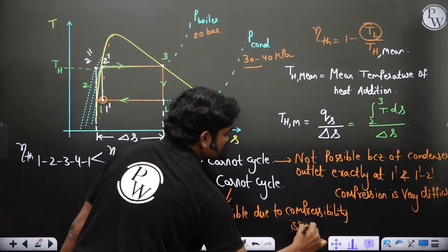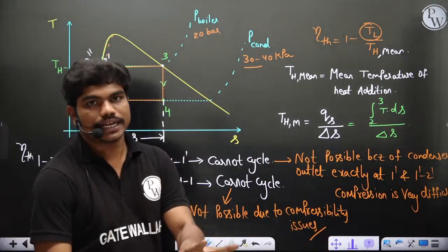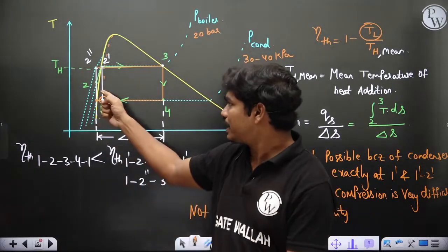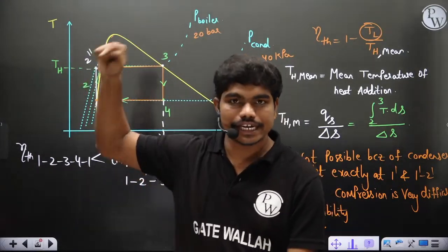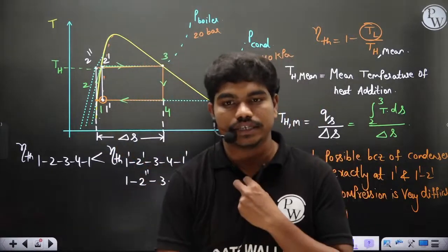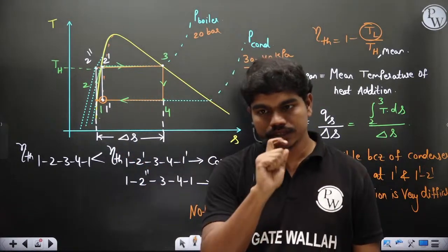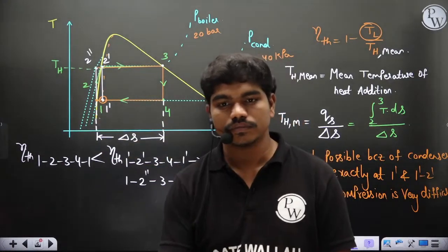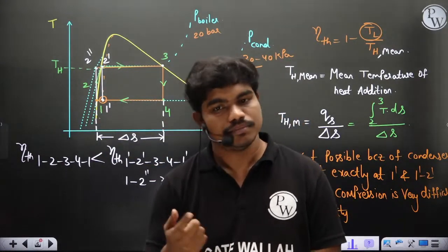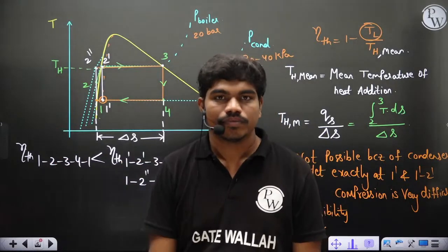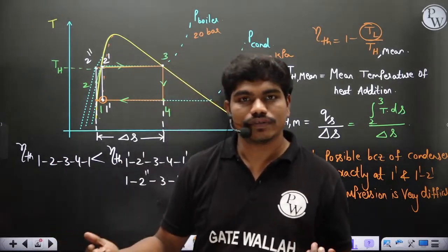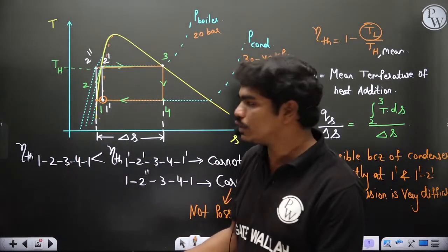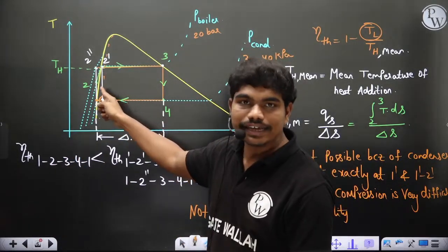Actually, so that's why the two possible Carnot cycles which can be done are eliminated practically, and that's why he has given a constant pressure heat addition process in the case of vapor power cycles. Clear? So did you all understand this logic, why all these things are important here? Because in interviews and all, if you go to BARC, people definitely ask you this. Why can you not generate a Carnot cycle? Because generating Carnot will definitely give you higher efficiency, but why are you not able to generate Carnot? Many people think of this and say work done will decrease actually, okay?